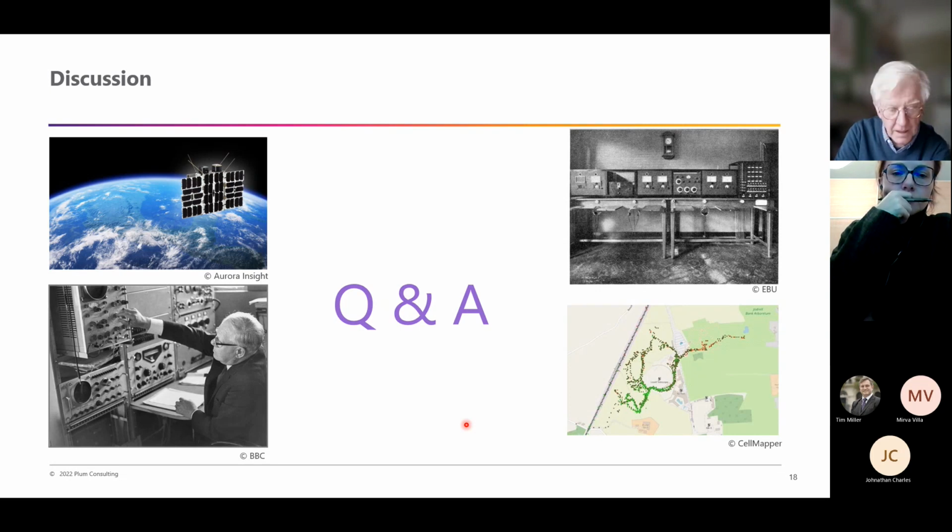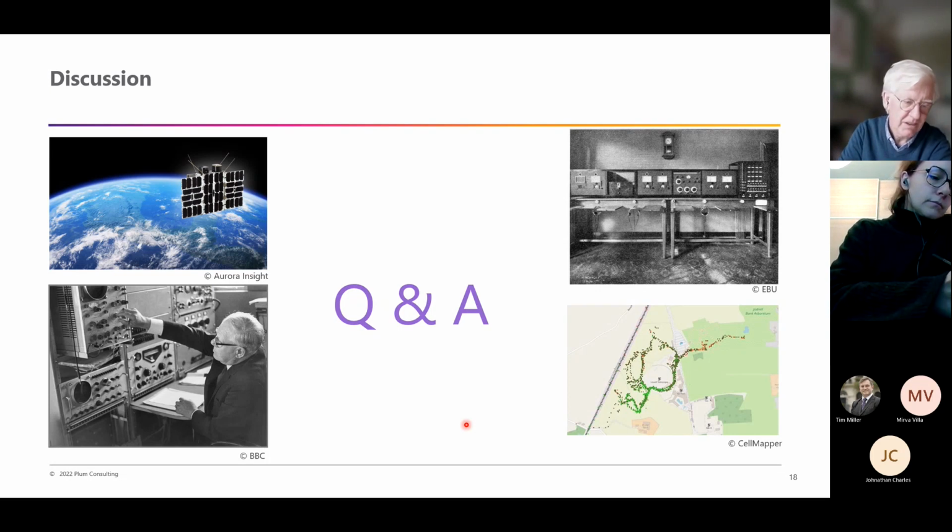That's one option. And mobile measurements are potentially possible if you have access to some very expensive hardware that can use active antenna systems to synthesize high gain antenna beams while you're traveling. So these are the sort of systems that are really being developed for things like satellite Earth stations in motion, if you're trying to provide services from geostationary or non-geostationary satellites to vehicles.